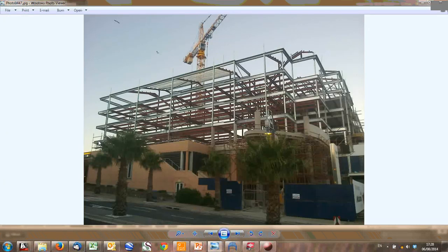Well, diaphragms, you've got the floors, so you can use your concrete floors to take the load to your lift shaft, which is a nice stiff poly structure. To analyze every little bit and piece is going to be a nightmare to get the loads on your lift shaft. So you just take your tributary area and pressure and suction. You can quickly then get a horizontal load which you apply to your lift shaft, and you can size your lift shaft or your brace floor or whatever it is that provides lateral stability.